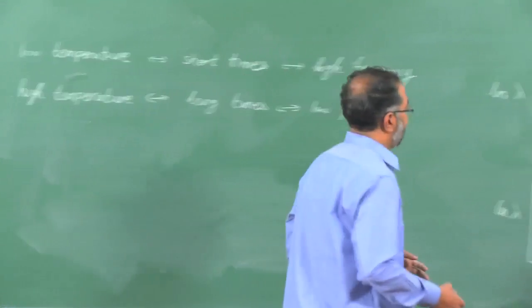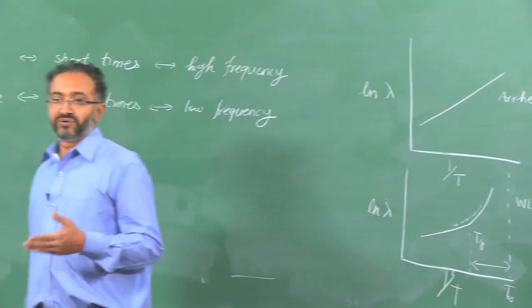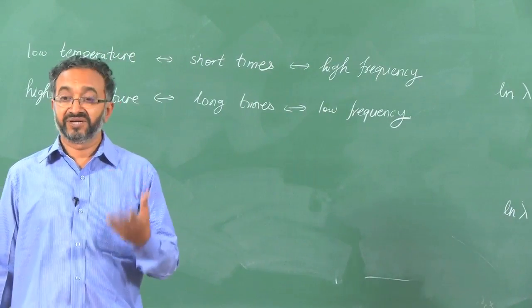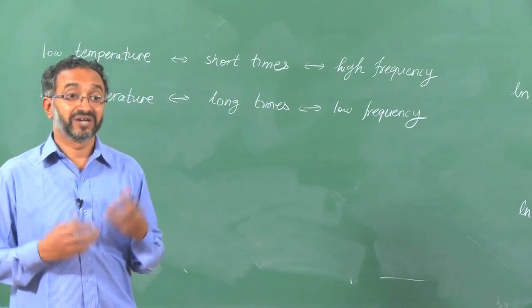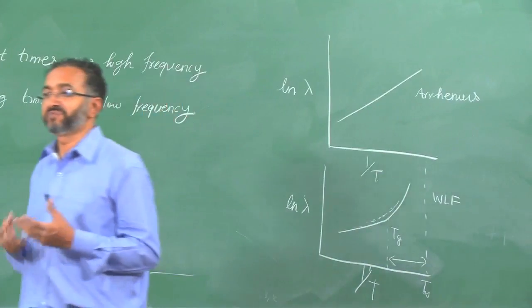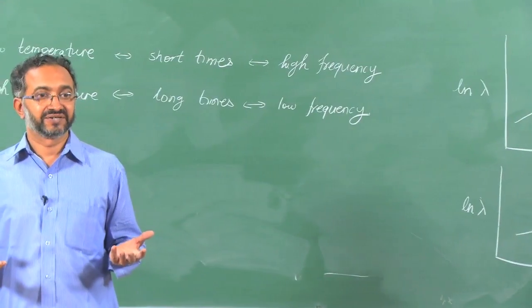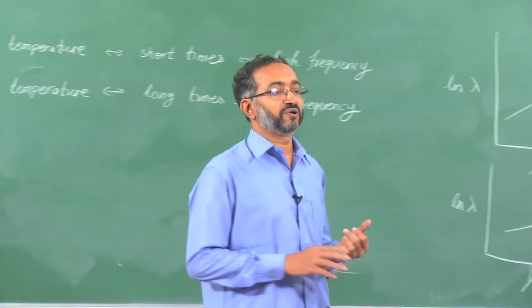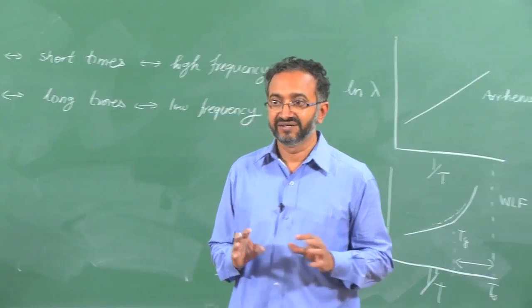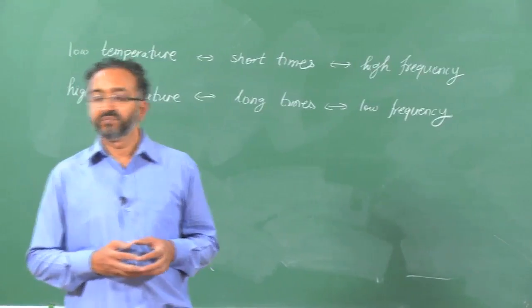And so, WLF, Williams-Landel-Ferry, is an empirical equation. In the 60s and 70s it was observed that, miraculously, for a large number of materials one equation seemed to fit all the data, and so people were thinking that maybe there is some universal WLF equation which is valid for all materials. We know now that, first of all, it is valid only for materials which do not undergo large changes as a function of temperature, and secondly, the constants are not necessarily universal.